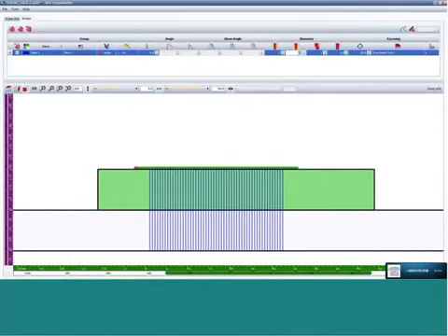This group can be directly exported to a file called a connectivity file that allows it to be put on the flash card of the instrument and imported directly. It can be generated as a law file, similar to the calculators like the TomoView calculator, or you can quickly copy this and create the same setup using the OmniScan MX2 wizard.